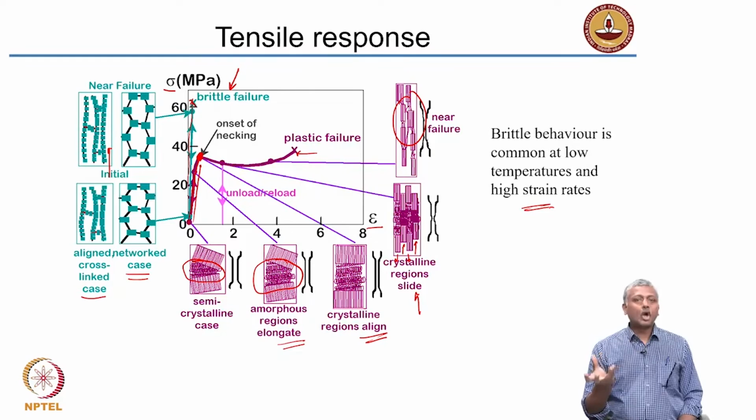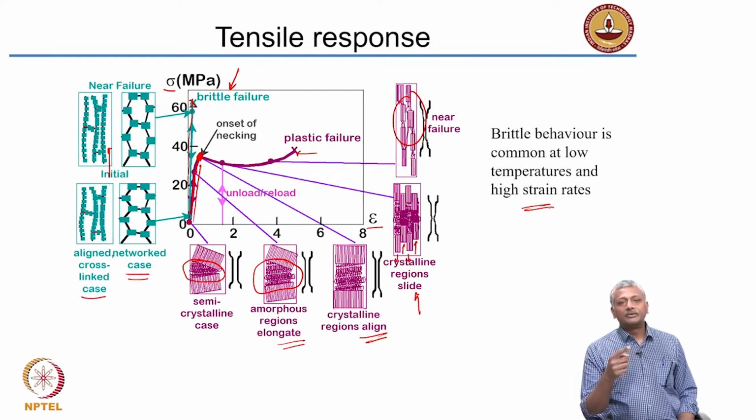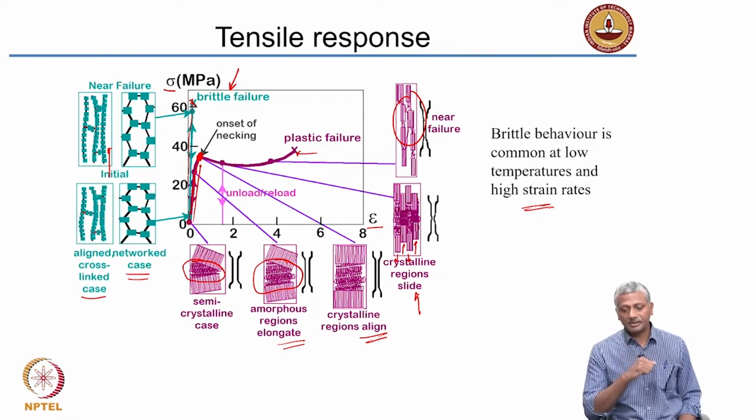Now, when you deal with common polymers, let us say you have your water bucket. You will see that with multiple uses, the bucket starts cracking. Why does it start cracking? It is because the material has become more and more brittle. In response to age, it has become brittle, age implying exposure to ultraviolet radiation. That is another aspect that can change the properties of the polymer significantly.